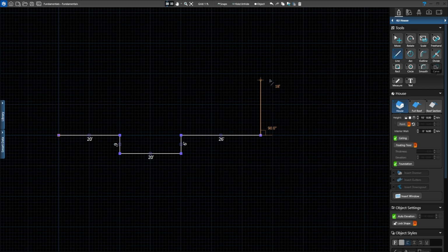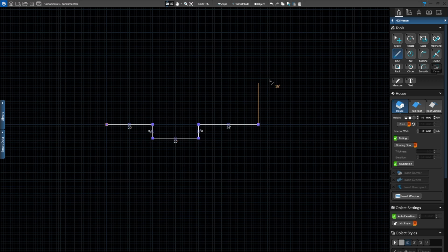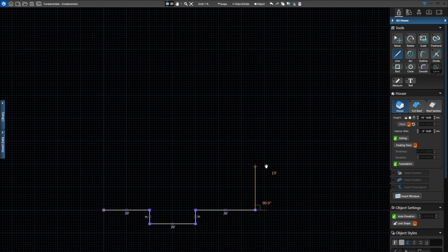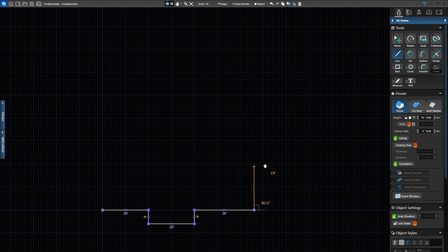We're now drawing up the right side of the house 74 feet. So that's a longer line segment. I may want to either zoom out or pan down or both. I can roll my scroll wheel toward me to zoom out, press down on my middle scroll wheel like a button to pan down. That's going to give me enough room to draw up 74 feet.